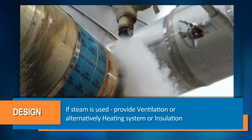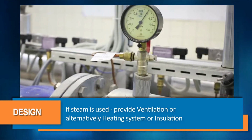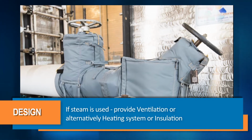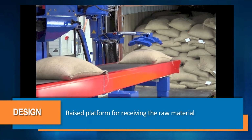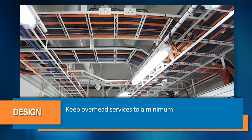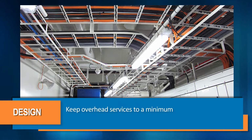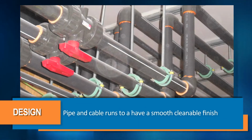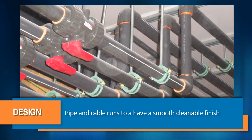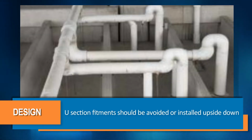For example, if steam is used in the process, ventilation shall be provided, or alternatively, a heating system or insulation may be designed to prevent condensation. There should be a raised platform for receiving the raw material. Overhead services such as cable trays and pipe runs should be kept to a minimum, and if possible, a suspended ceiling installed beneath. Pipe and cable runs should have a smooth, cleanable finish. U-section fitments should be avoided or installed upside down to prevent dust and dirt from collecting.